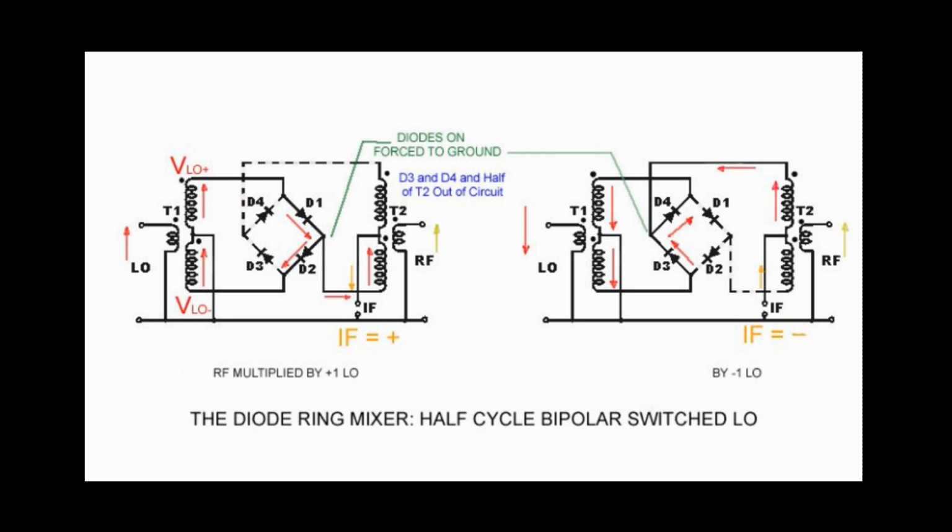So the operation of the mixer can be thought of as a square or sine wave multiplied by the RF signal. The local oscillator basically creates an oscillating RF signal with positive and negative polarities. This is equivalent to multiplying the RF by a square wave going from -1 to +1 at the local oscillator frequency. Some other things of note while we're looking at this thing.